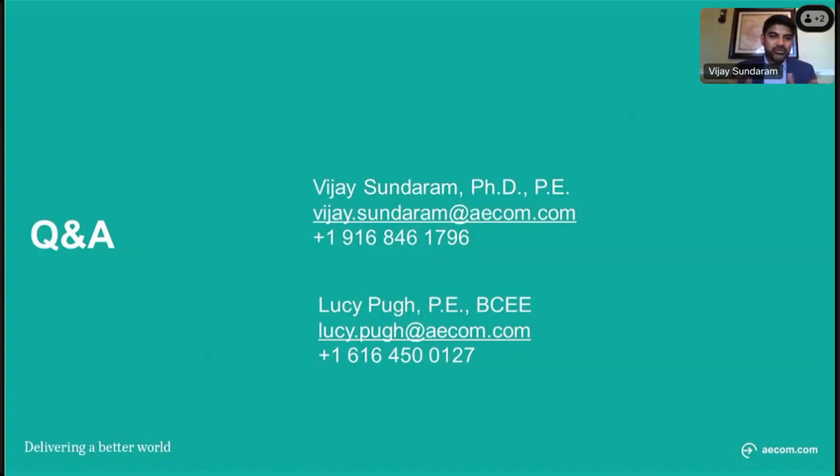So that's my big picture answer, that it is very, very problematic for community scale to deal with those concentrates. However, I mentioned ozone biofiltration and other technologies that avoid the use of reverse osmosis. And from the big picture, if you're in coastal areas, the practice is to put it in an ocean outfall and dilute it, which is okay.